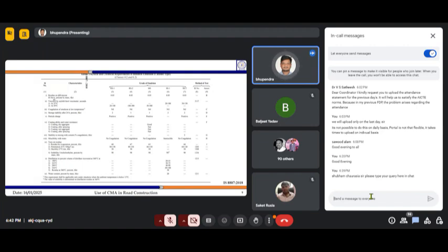That is for checking the purity of your emulsion, whether any foreign particles are present in it or not. It should be less than 0.05%. Then we check the viscosity, and based upon the viscosity only, the grade of emulsion is determined.